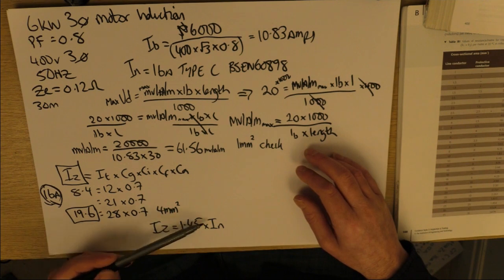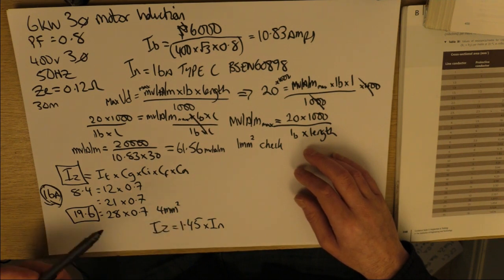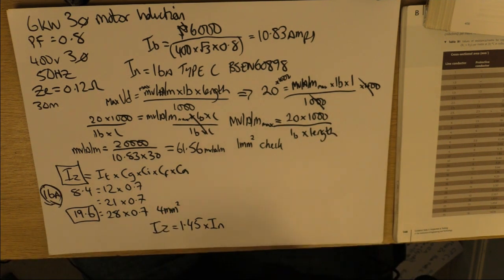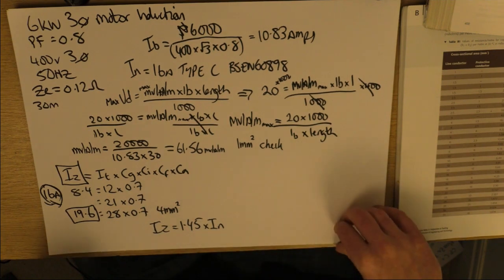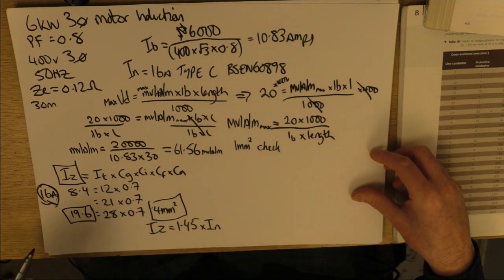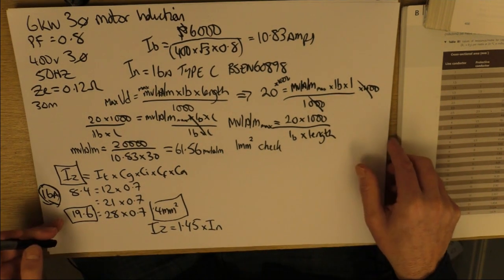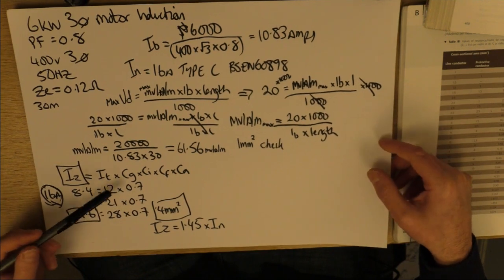Also consider lighting circuits. People are going to add to them. So again, you might want to allow for it there, but that's down to the engineer's judgment. Now, so we've got our 4 mil. It complies with volt drop, as we know, and it's just a different way of getting there, but you can see there's still a bit of back and forth here.